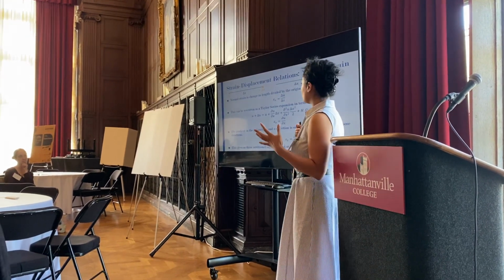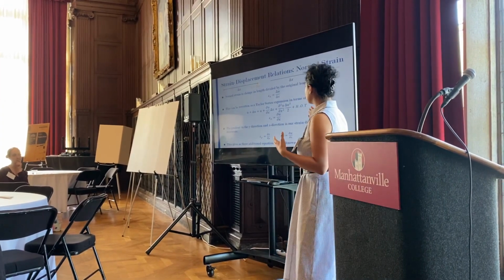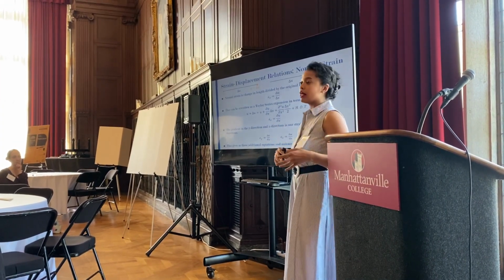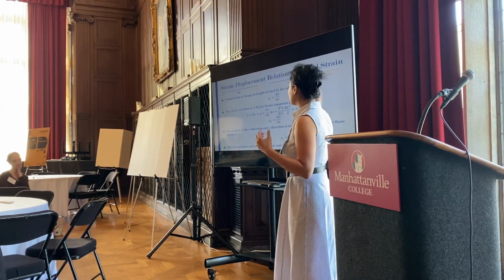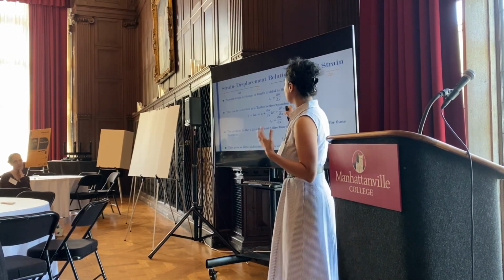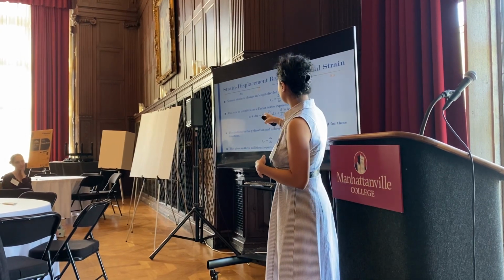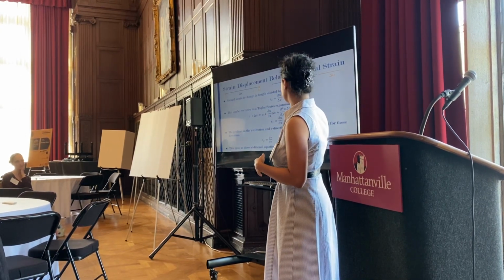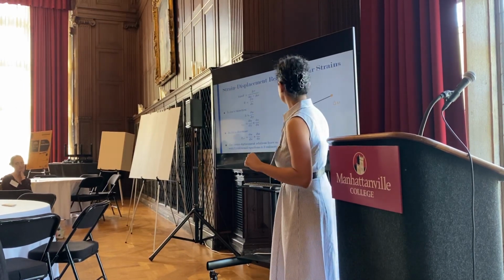And for this as well, we take our favorite tool, a Taylor series approximation. And again, because we're dealing with infinitesimally small elements, the dimensions can be taken out in the higher order terms, which leaves us with our normal strain equaling the gradient of u in terms of x. The same can be said for the normal strain in the y direction and in the z direction. So that's an additional 3 equations to our system.